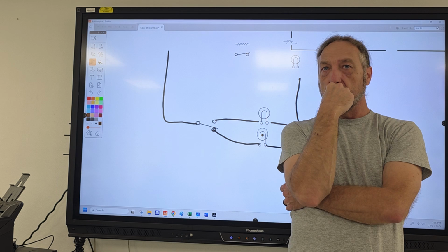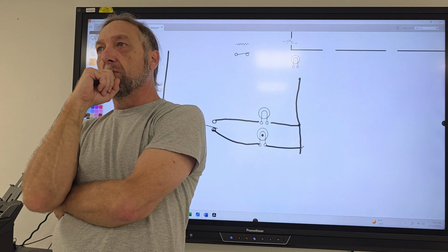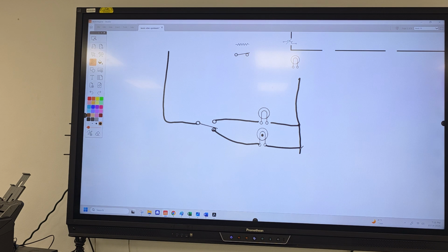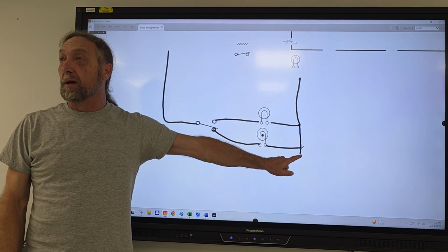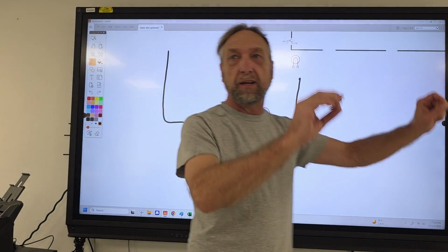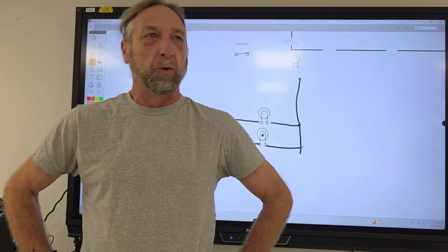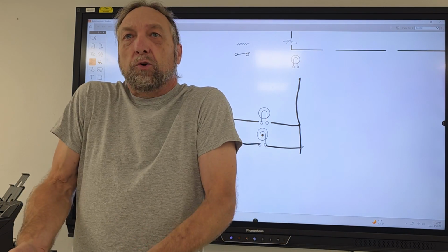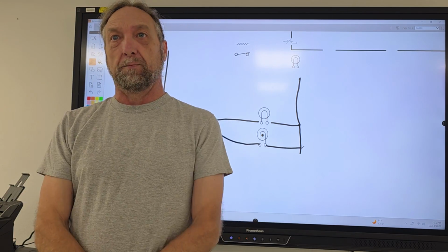Maybe see which contacts are used in that circuit. Good job, bro. You go to the diagram and you look at the self-clean circuit, and we're gonna look at all those switches in the diagram. Well, guess what? That blue wire's in that circuit. Guess what? The diagram don't show that blue wire. Now what? The manufacturer glued the wrong diagram to the machine.